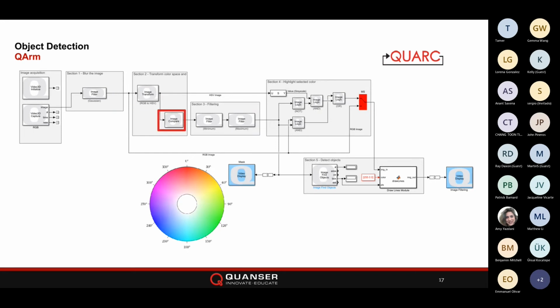Using the image compare block, we can select the range of values that we are interested in. This will output a bitonal mask image that we then filter to take the noise out. Using some image logic blocks, as well as the value plane of our HSV image to obtain a grayscale, we can create a grayscale image that will only color the areas of interest based on the mask. Don't worry, we'll show you this in the next video.